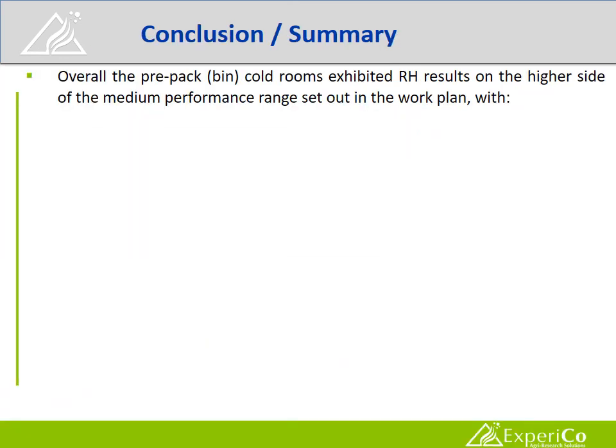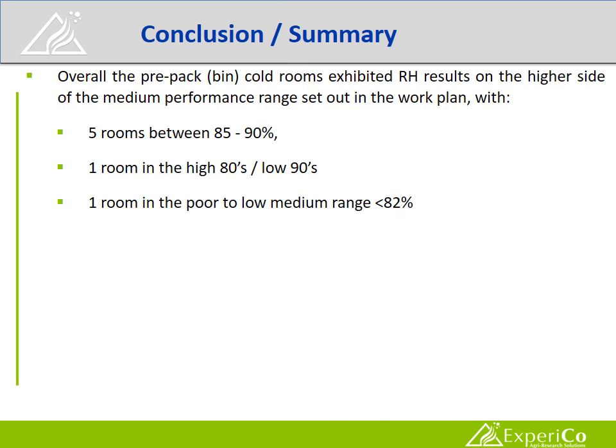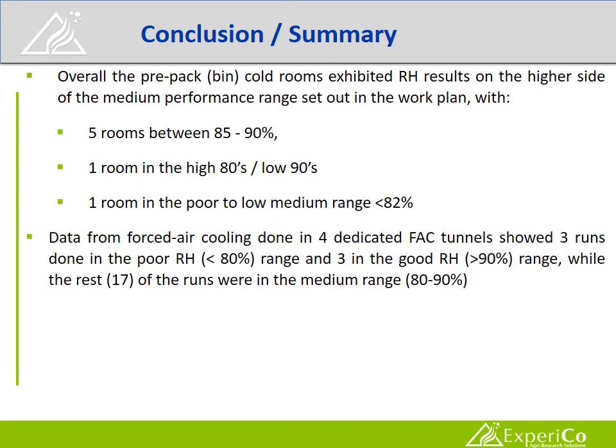If you look at the conclusion summary, overall the pre-pack bin cold rooms exhibited RH results on the higher side of the medium performance range set out in the work plan, with 5 rooms between 85 and 90%, 1 room in the high 80s to low 90s, and 1 room in the poor to low medium range, and that was below 82% relative humidity.